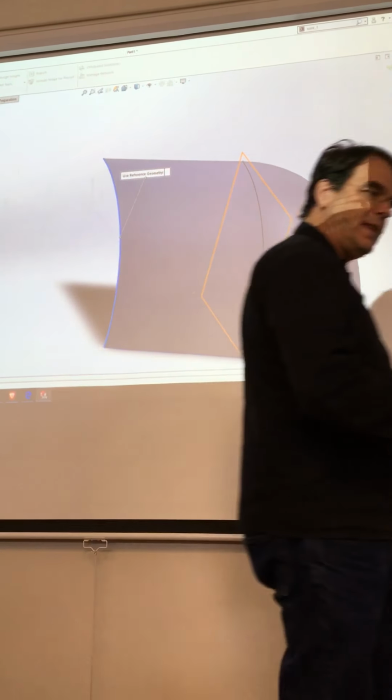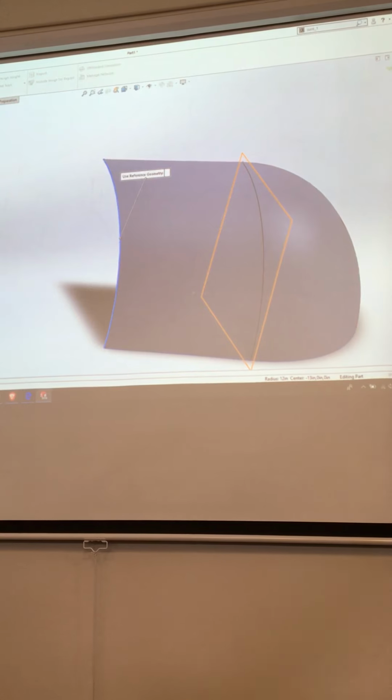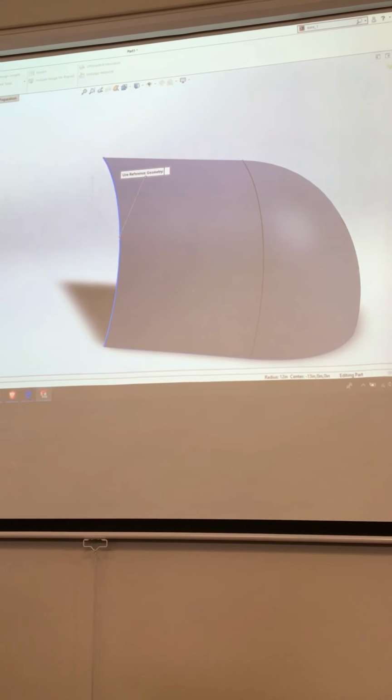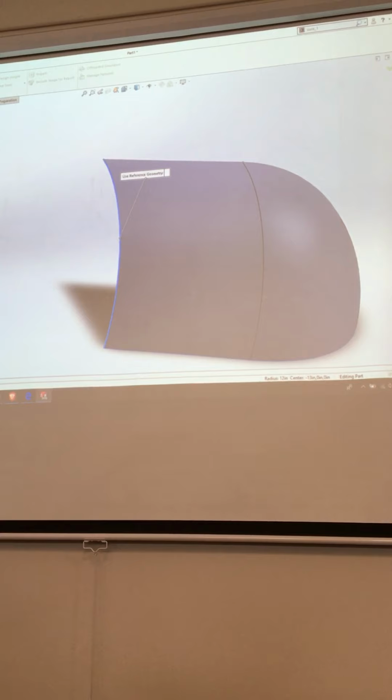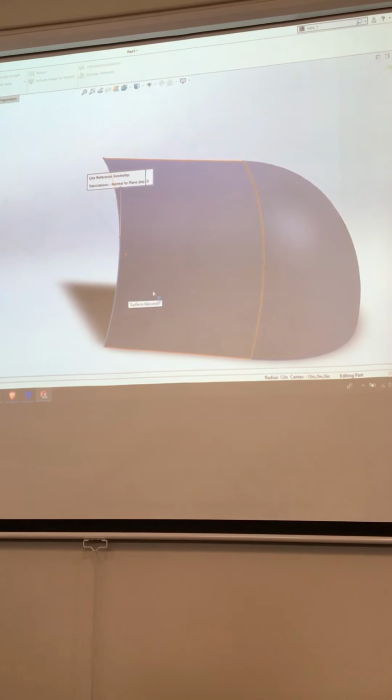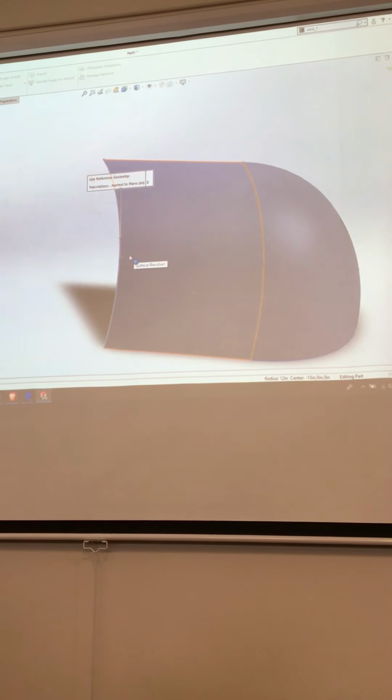Now, that's not the only part of the symmetrical boundary condition, okay? So I can come down here to my boundary conditions and I fix the out of plane boundary condition, right? And it doesn't give me any arrows, or it gives me arrows that are really small. So I'll have to go fix the arrows.